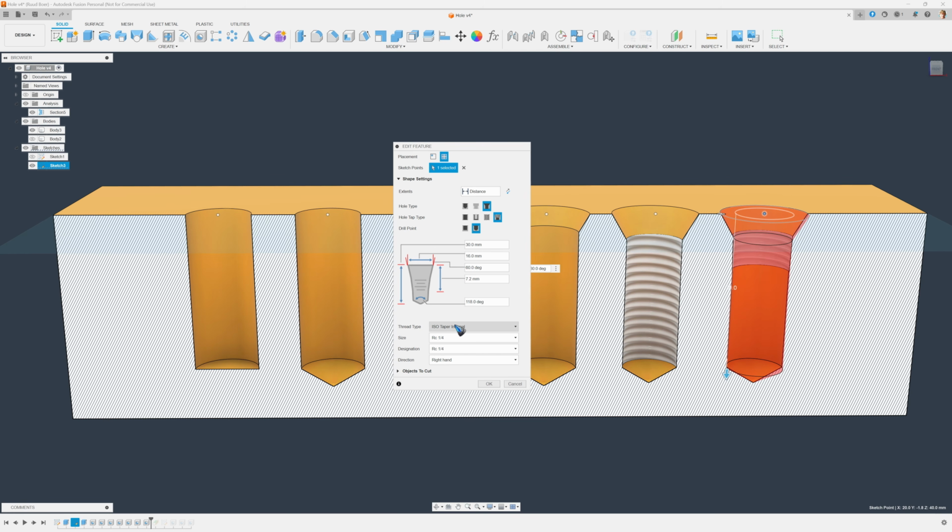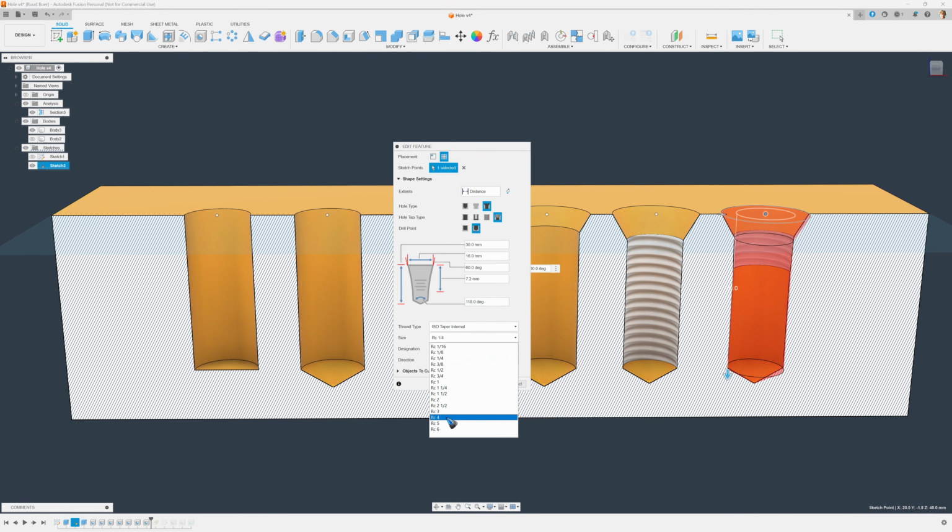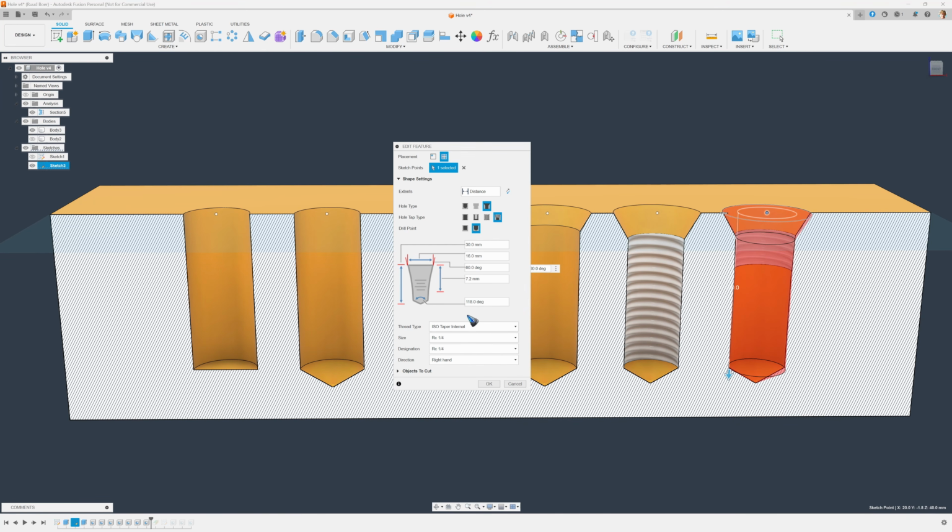Over here at the bottom there's also a sort of engineering system. You can specify specific types of holes, and you have all the official specifications that go along with that. So if you want to use those boxes, then you get the hole that you specify in those boxes, and you don't have to fill in any numbers over there anymore.